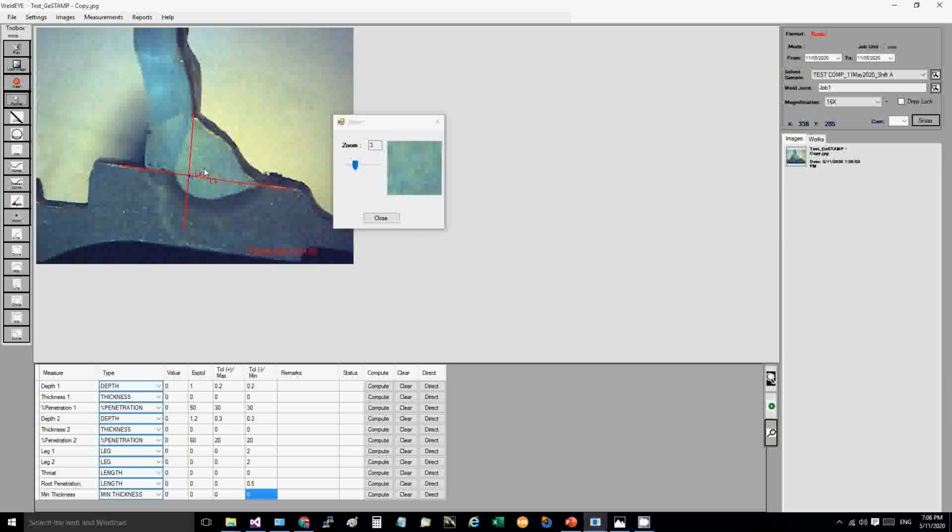So these are some options that I am showing you so that you will get an idea about the features and options that you are going to have. System then will automatically find out the intersection points. Now if you see, this is the weld bead, my profile of the weld bead, my penetration here, and this is my penetration on this point.